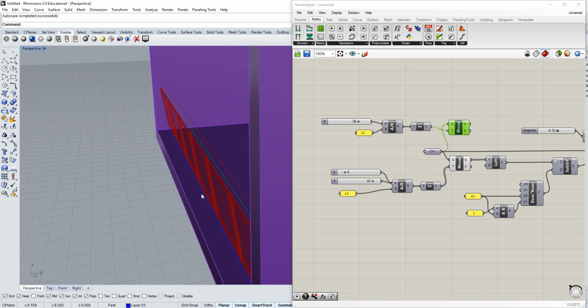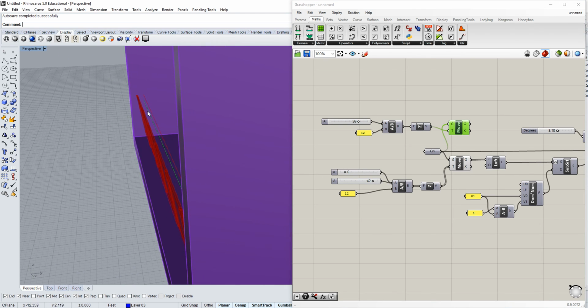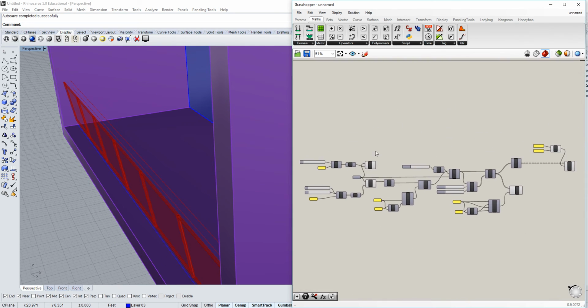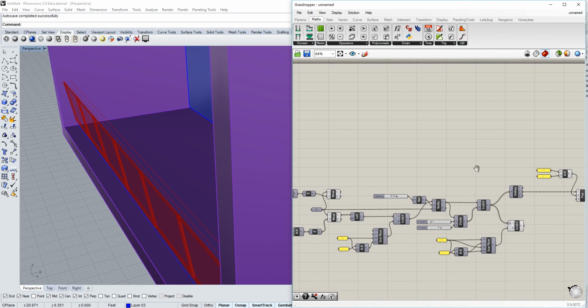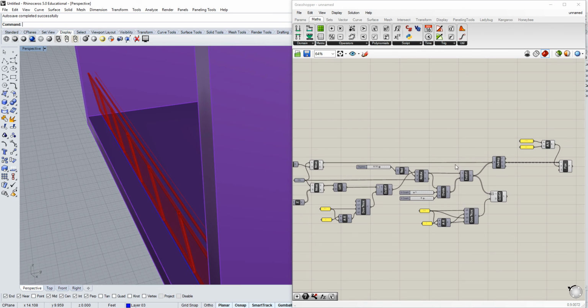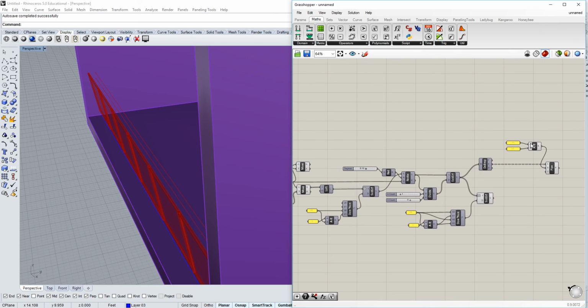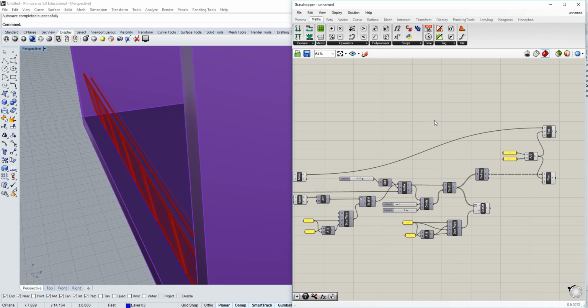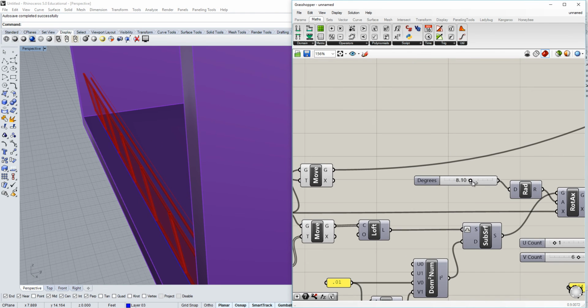So now I've got a pipe center line that's going to sit 36 inches above the ground, directly above the bottom rail. And the pipe for this one is really as simple as, if it's going to be the same diameter, you can just plug it in directly to this pipe, and that's going to work just fine. Otherwise, if you wanted to make it a different material, you can just copy it up and then override the connection right here, and you've got a secondary pipe. And that will stay static as this rotates.